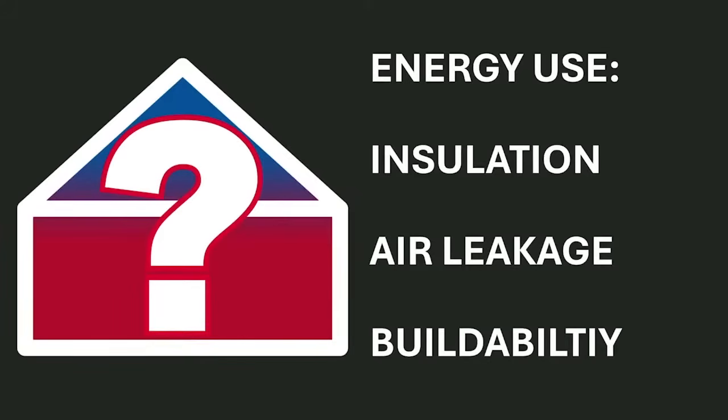A more fundamental consideration is the general suitability of cold roof constructions in buildings where air tightness and energy use are the primary focus, such as passive and low energy homes. Roof specification can have a major effect on the overall heat loss from a building, but increasing thermal insulation levels and reduced air leakage must be accounted for in the hygrothermal design. We must also consider the performance gap between as-designed and as-built performance. Warm roofs, particularly those constructed off-site, typically simplify meeting these goals reliably on-site, but there are other environmental factors to consider.